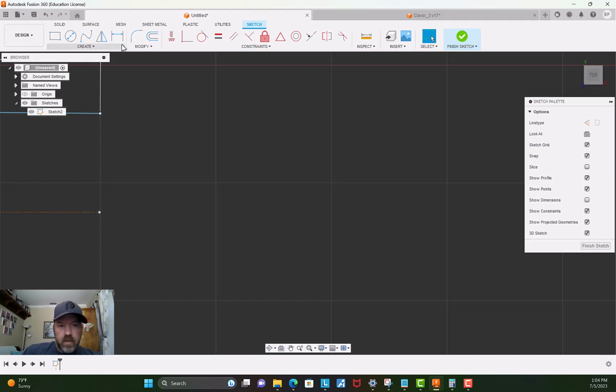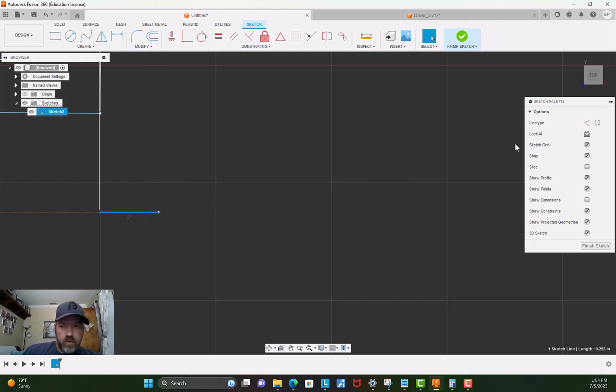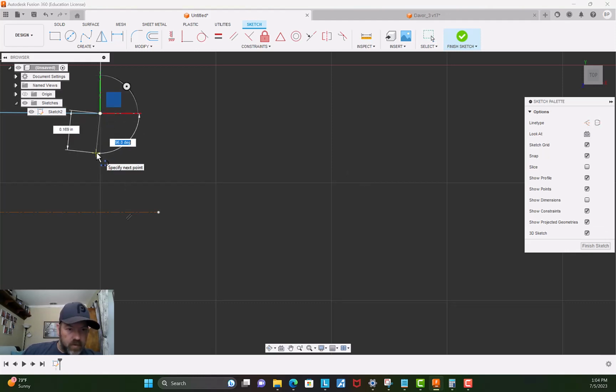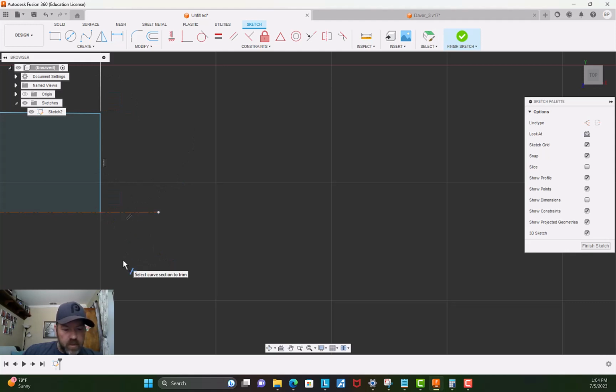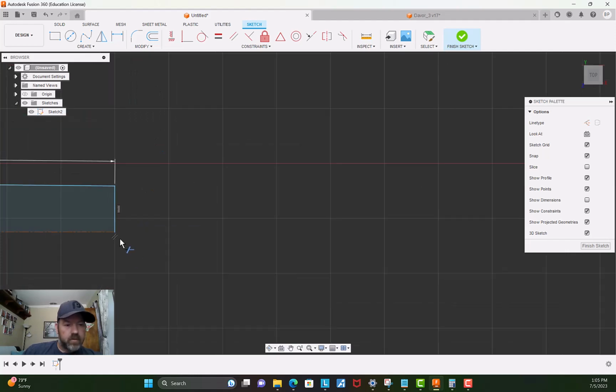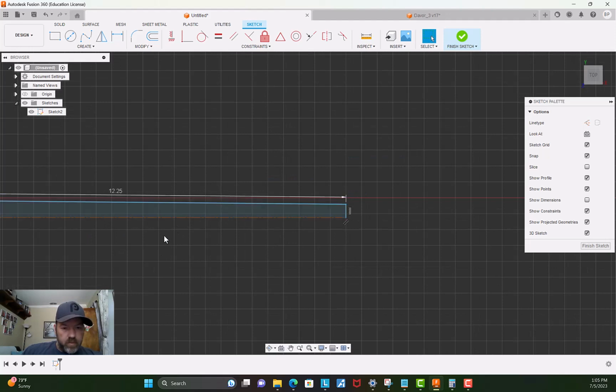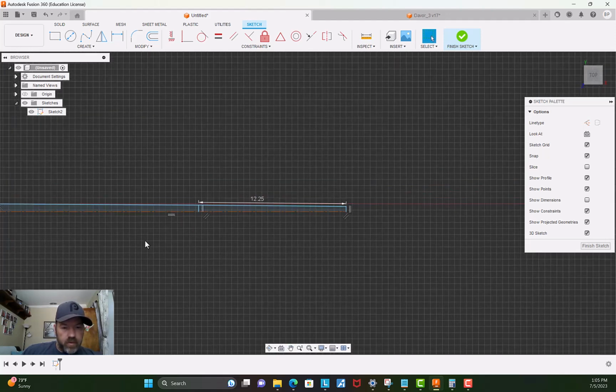Let's just extend this one another 0.2 inches. And now let's try again, 90 degrees, and I want to snap it to here. There we go. Now let's trim off the rest with the T. You can either go to modify trim or hit the T command and trim it off. Okay, now if we hover, we can see we have this shaded profile here and shaded profile there.